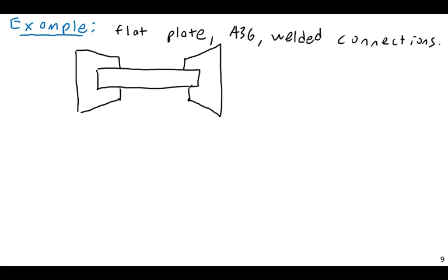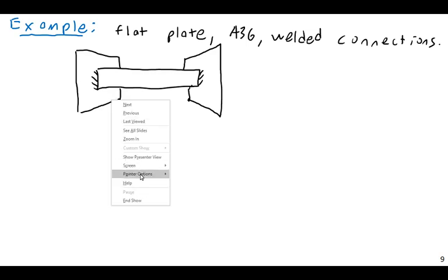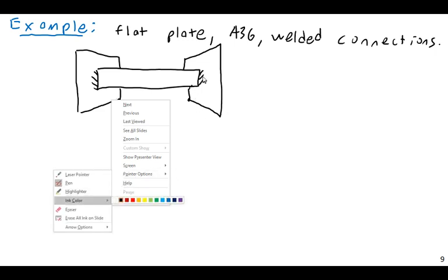And I'm going to weld it just here. So effectively, because of this very particular type of connection, I'm forcing this thing to fail in the yielding state, because it's only connected at its ends, so it's not really going to undergo fracture.